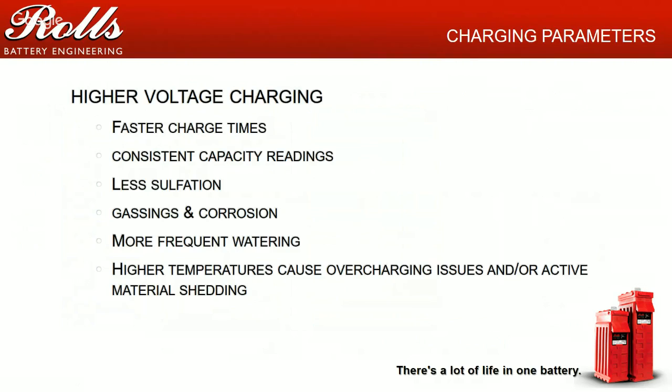One of the things I always tell people, especially when it comes to charging their batteries, is it's cheaper to replace distilled water than it is to replace batteries. So with the gassing, yes, you're going to have to use more water and do a little bit more maintenance, but it's better to do that than to have to worry about running multiple equalization charges or having batteries that die after three or four years of use anyway.